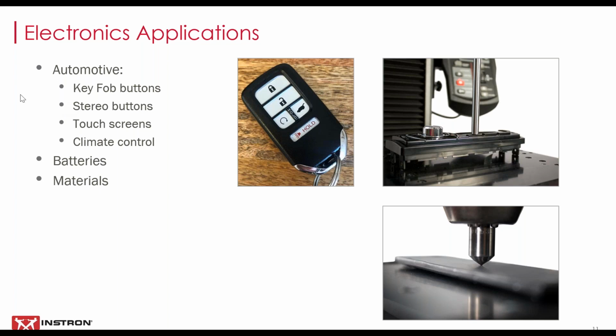And even in addition to components and parts and devices, you also have just the more general materials testing. The XY system can perform tension, compression, or bend testing on small specimens that might be used for QC testing, or even to characterize new materials that are being developed. Using an automated XY stage for any of these applications would provide all the benefits that we've been discussing: throughput, efficiency, and repeatability.